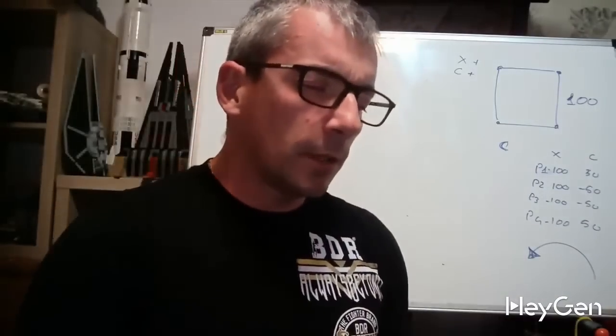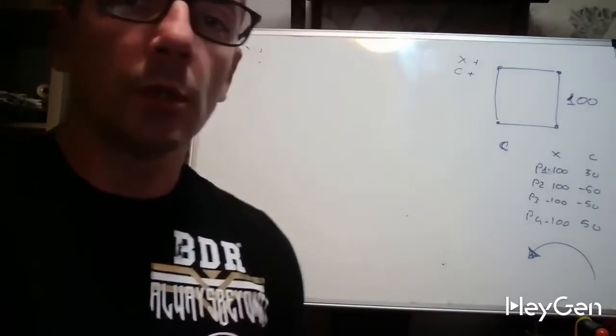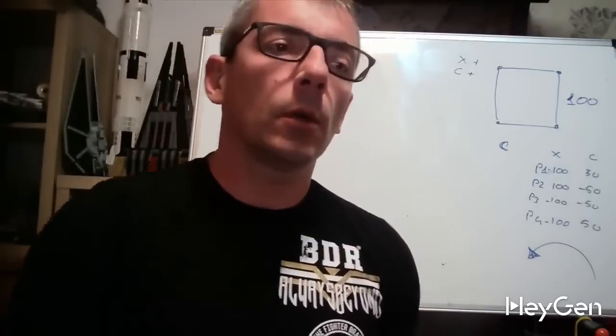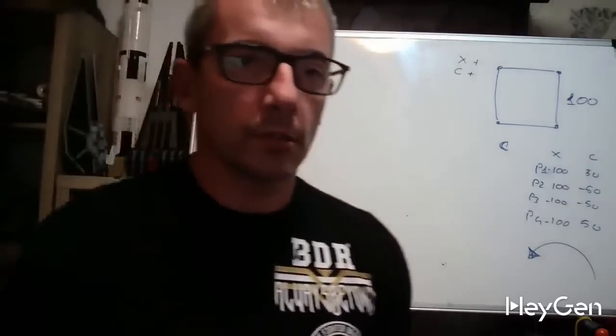Some people use it that way. But G112 tells the machine, look, we are working with polar coordinates related to the workpiece.